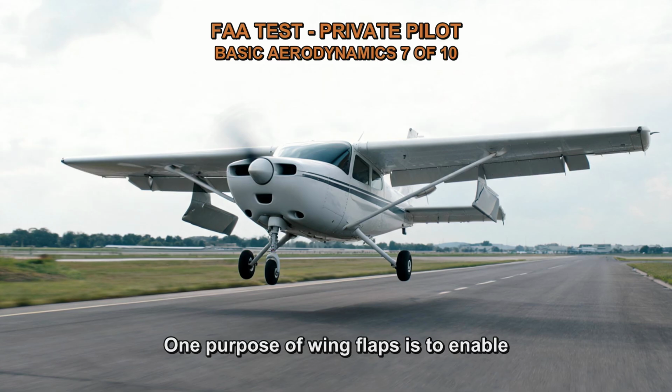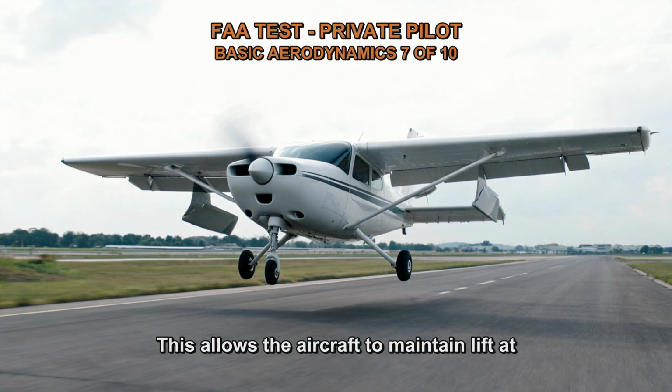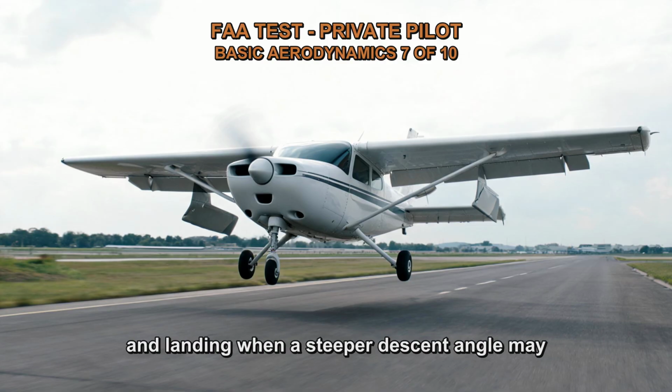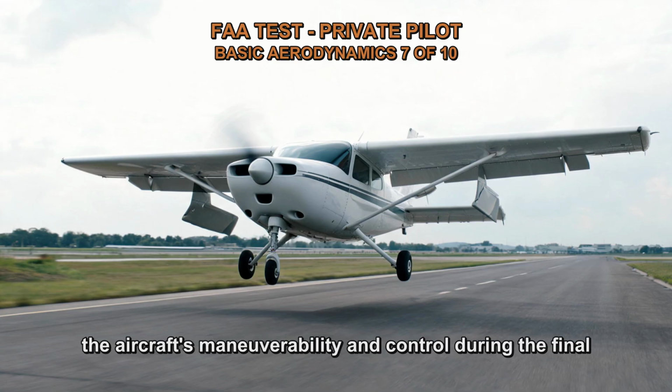One purpose of wing flaps is to enable the pilot to make steeper approaches to a landing without increasing the airspeed. By extending the flaps, the effective camber of the wing increases, resulting in increased lift and higher drag. This allows the aircraft to maintain lift at lower airspeeds, which is particularly useful during approach and landing when a steeper descent angle may be required. The increased lift provided by the flaps allows for slower speeds and shorter landing distances, enhancing the aircraft's maneuverability and control during the final stages of flight.